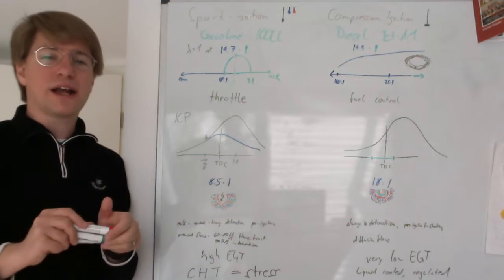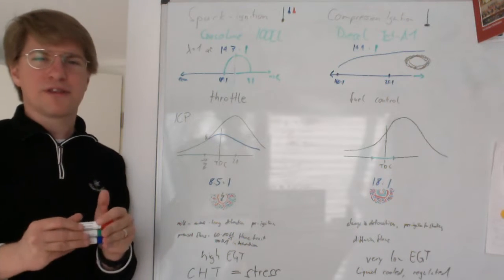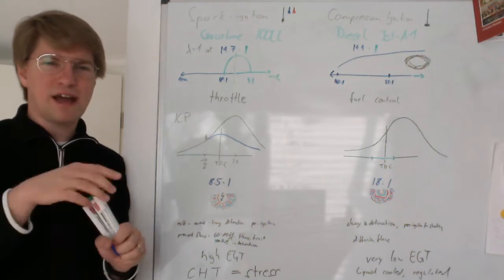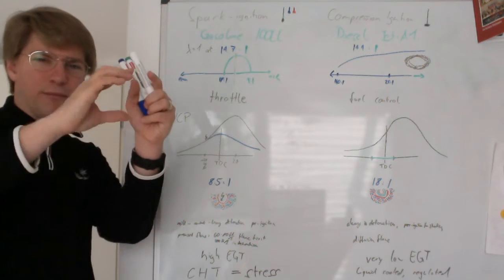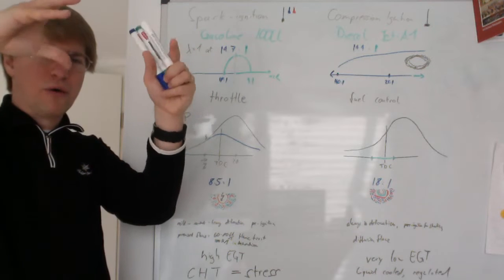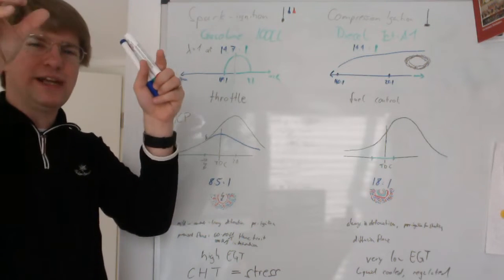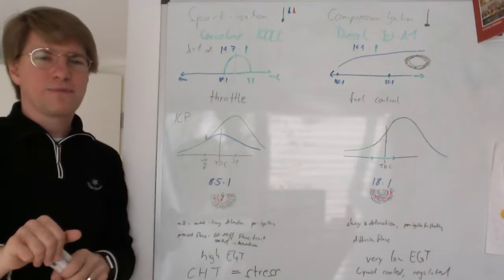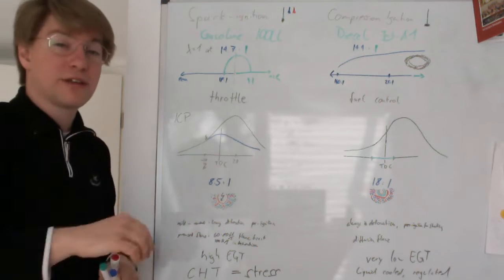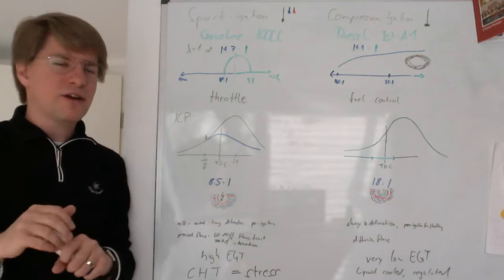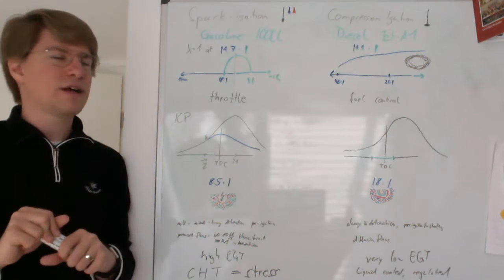Now, modern car engines do a lot better with fuel stratified injection. They can have localized pockets of a richer mixture, whereas the whole combustion chamber is much leaner than this local pocket. So with modern direct injection, fuel stratified injection, you can do a lot better than 18:1. But this is technology that is not available to us in our aircraft engine.